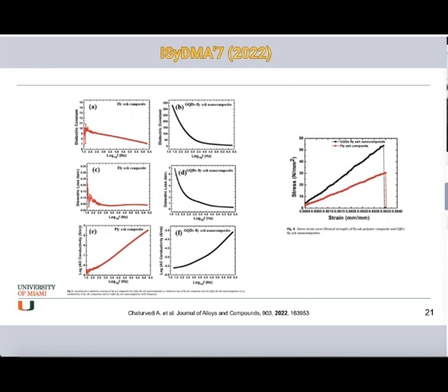This rapid increase in the dielectric constant is ascribed to the formation of large electric dipoles per unit volume due to the nanoscale size of the fly ash and carbon dust nanoparticles, and motion of the free charge carriers due to the formation of conduction pathways in the carbon dust, fly ash and epoxy.